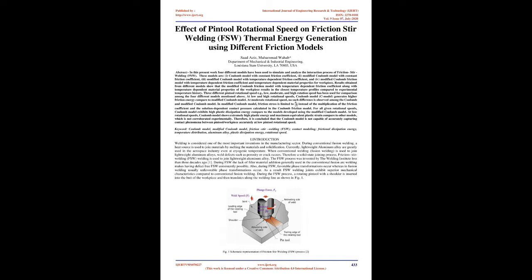For all given rotational speeds, Coulomb model exhibits high plastic dissipation energy compared to the models developed using the modified Coulomb model. At low rotational speeds, Coulomb model shows extremely high plastic energy and maximum equivalent plastic strain compared to other models, which is not corroborated experimentally. Therefore, it is concluded that the Coulomb model is not capable of accurately capturing contact phenomena between pintool/workpiece at